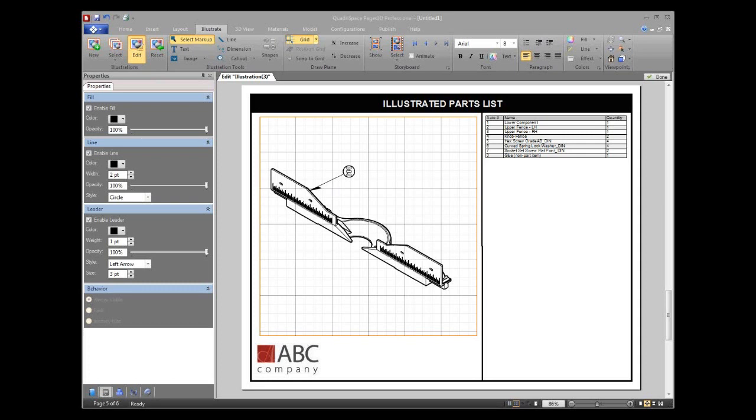Also, 64-bit allows the use of more memory, which means for big models, where a lot of memory is needed, that'll open up that memory for the use of the larger models. And then we also have configurations, which is a great tool for working with large models. It allows you to chop down to those subsets and work with them, and you don't have the high overhead of all the large models hanging around all the time. But yet, you have the convenience of the single file that you can always go pull up any of the parts that you need from the model and leverage those.